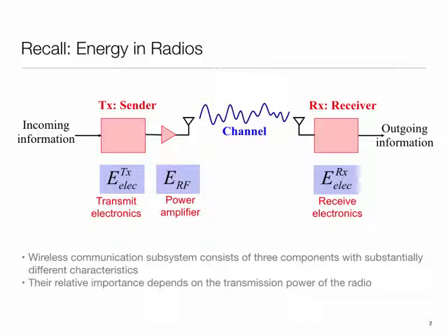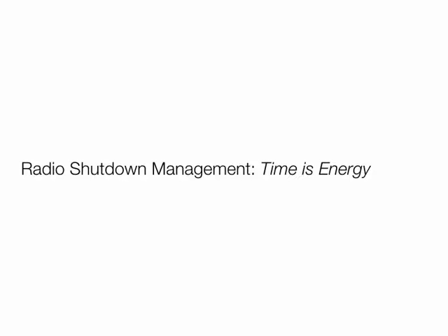But once we are in this regime where the right hand side dominates, a lot of those assumptions fall out of the window. In particular, no longer could you say that I can keep the receiver up all the time waiting for a packet to arrive, because the act of keeping the receiver up was the dominating thing. Now, in some cases, there is no choice.